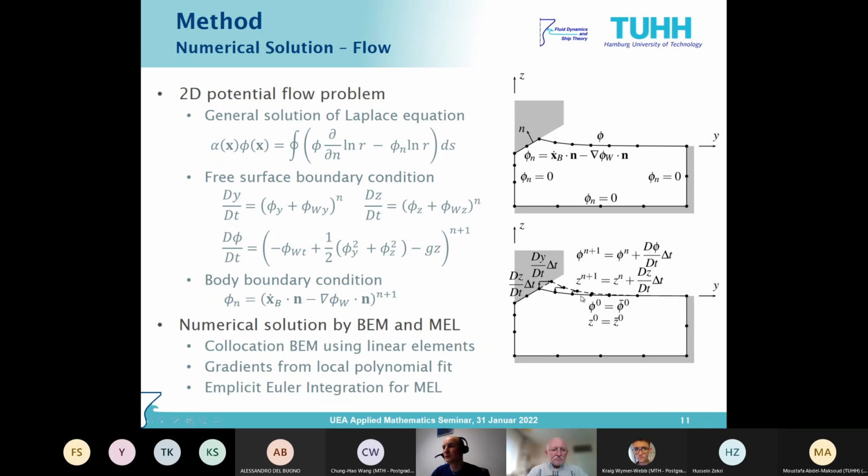Not always, not only. Also, if you don't remesh, then with time it may happen that some points will accumulate somewhere, or the grid distance will not be the same anymore. So this is one part of why it's better for stability. If you have some small numerical deviations, then you can smooth them with the regridding. It smooths the free surface, which is also good for stability. But you can also introduce some errors if you smooth too strongly.